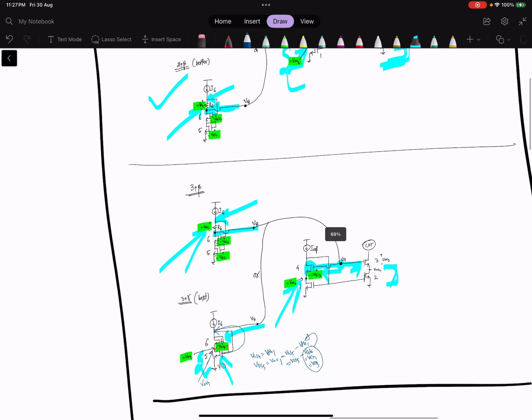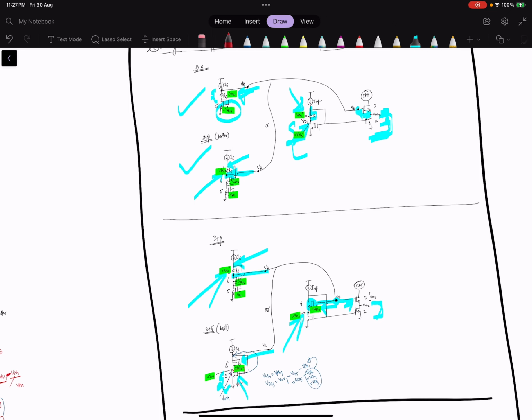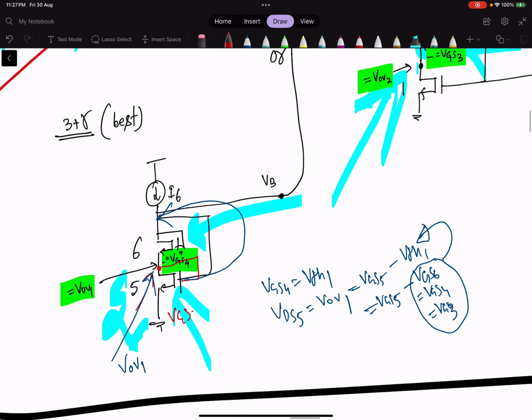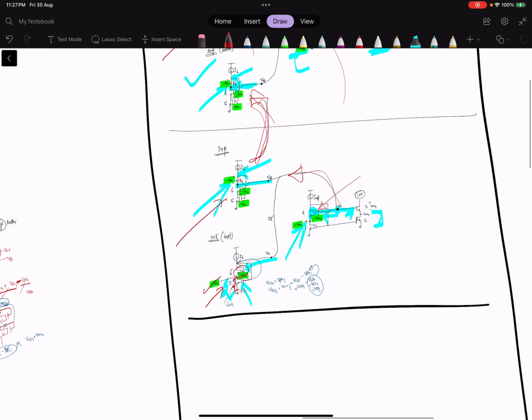So this final summary is, we have two circuits, one with R, one with MOS, and in this case VB is generated through the resistance and drop, and when we split the equation we have this, and here when we have generated the VB through the above, these two are the same. And another way is, we will forcefully design the circuit such that one drop is VGS and the other drop from the drain to source is equal to the overdrive voltage. So that is the summary.